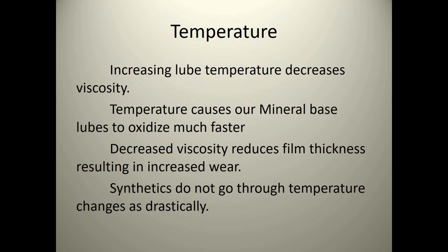Most of these temperature failure modes are based around mineral-based lubricants. And it says here mineral-based lubricants oxidize much faster at higher temperatures, so we have to be aware of that. If you've got things that are running 150, 160 degrees, you've got to plan on changing that mineral-based lubricant every year, and that's even if you keep the moisture out. If you have moisture in there, that lubricant may oxidize before then. But again, as viscosity decreases, we lose film thickness, and it results in increased wear of your equipment. So we always have to make sure we have enough viscosity to keep the components from running together.